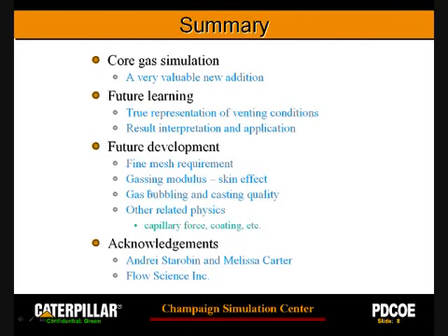And also, is it possible to develop some kind of a very quick, dirty model, just like I said, since heating is just a skin effect, maybe you can do something like a modulus type of approach, like cast metals, and really without doing this extensive simulation, you can really look at the core gas behavior of the cores.